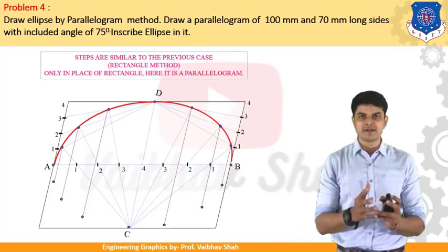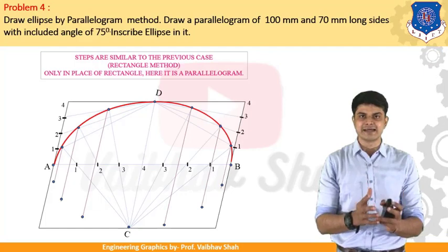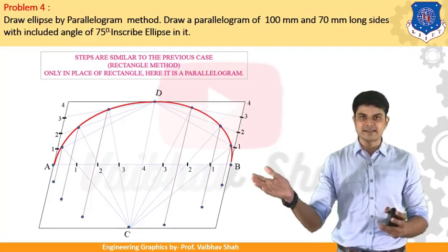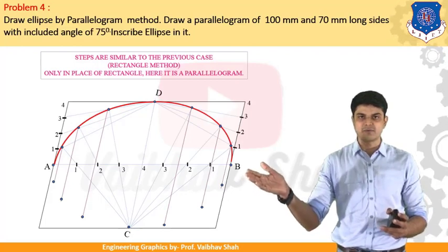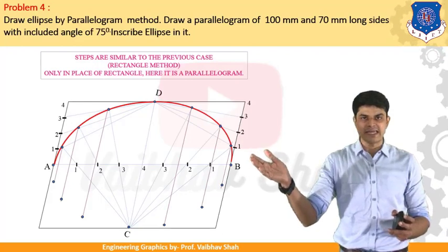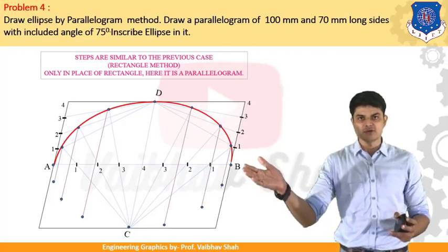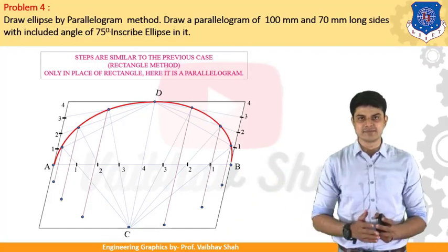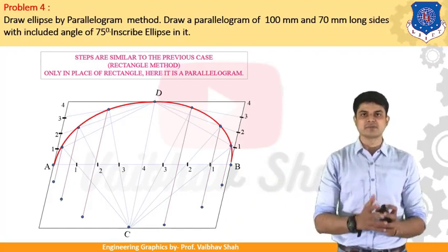So here what we are doing is defining one center line. The center line in this case is AB. So you will be taking the equal distance, which is the distance from your AB line to your point 1. On the above side, you need to take the same distance onto your rounder. You need to plot the same distance on that line below that line. So you will have points for each of the cases.